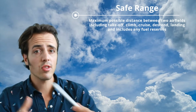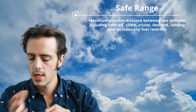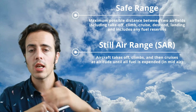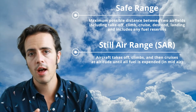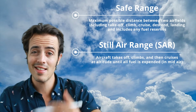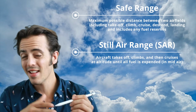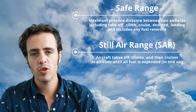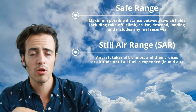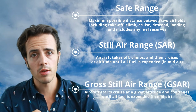After that, we then have a slightly more abstract version of range, which is the still air range. The still air range starts exactly the same. We take off, we climb to altitude, and then the aircraft flies until the point that all fuel is expended. At that point, that defines the still air range, or SAR, of this aircraft. That's still a little bit too complex for this course because we're not looking at calculations of fuel in either takeoff or in climb. We're going to look at something called the gross still air range.